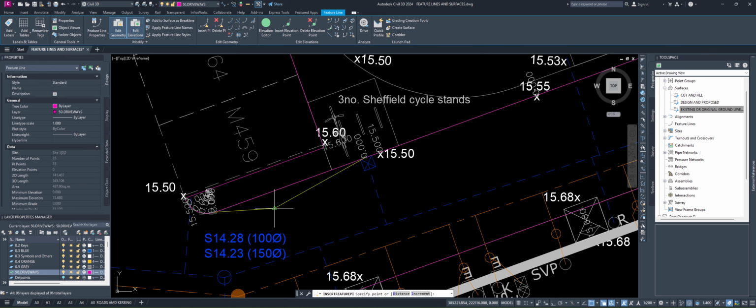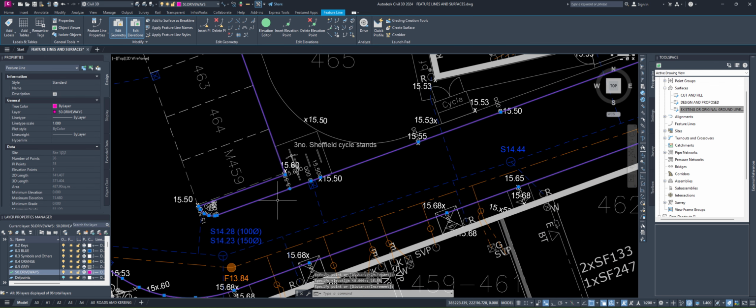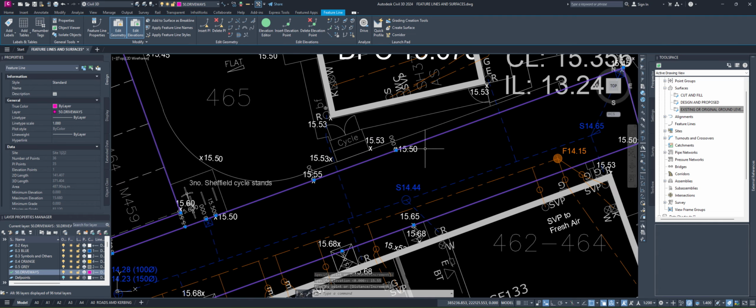Okay, I don't want to change the direction of the line, that's why I'm going to hit escape. I'm going to go again to insert elevation point. And now let's say we're going to create a point somewhere up here, which is going to be halfway between. Now let's create something like 15.550 up here. Okay, let's go 15.550 elevation, and now we create some sort of high point.